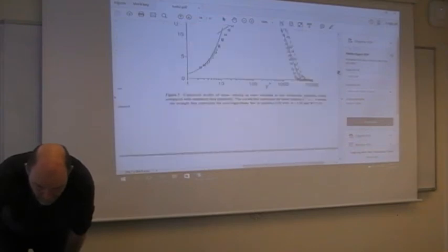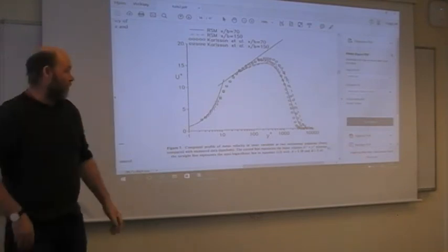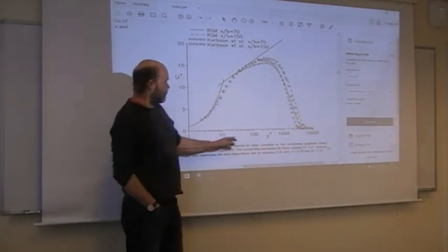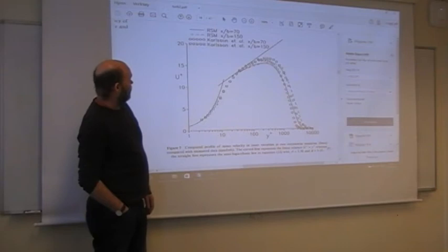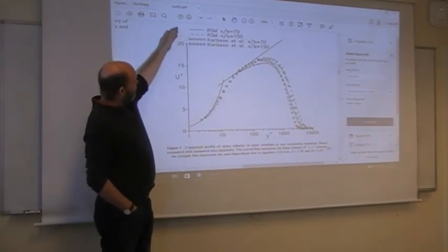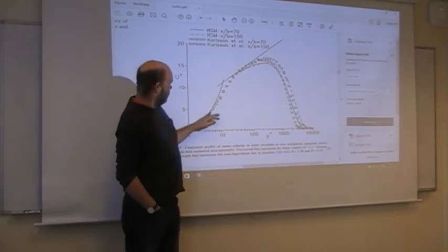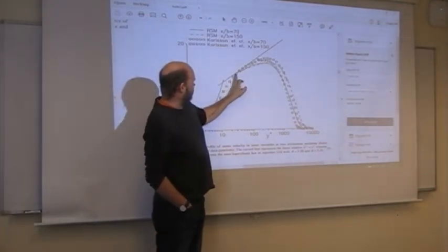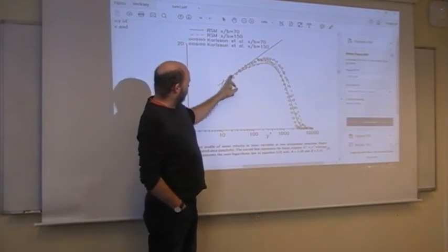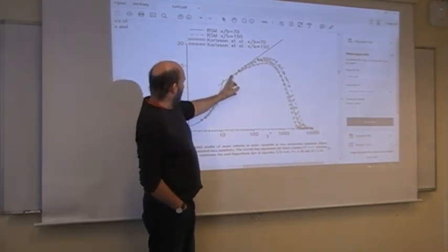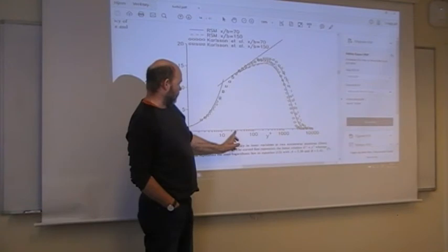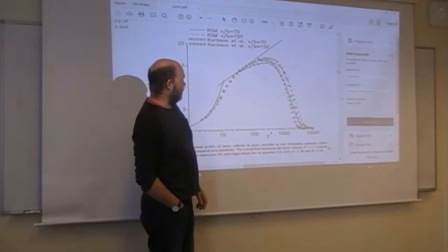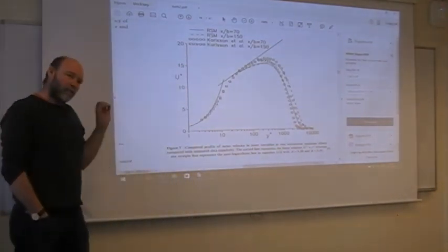So the mean velocity profile is very important to get correct. And here plotted in turbulent wall units, plus units, the RSM follows the log law fairly okay in the beginning. So you see its closest position here, close to the wall, is 25 or something in plus units. So it's fairly far away from the wall at the first grid point.